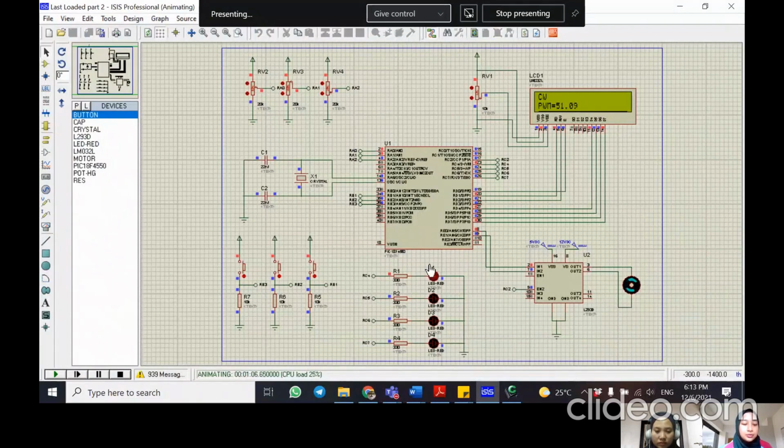From 81 to 120, two LEDs will turn on. Next is 121 to 140, three LEDs will turn on. 141 to 180, all of the LEDs will turn on. And the last one is 181 to 255, the LED will blink and the delay is around 200 milliseconds.